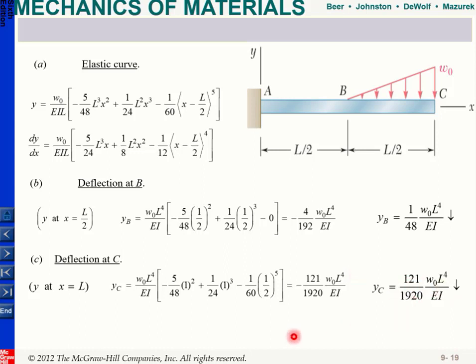Okay. So this singularity functions approach is really useful if you need to look at a beam and find the deflections or slopes at different points. Otherwise, if you just try to look from A to B, you cannot just get one moment and try to solve all the unknowns.